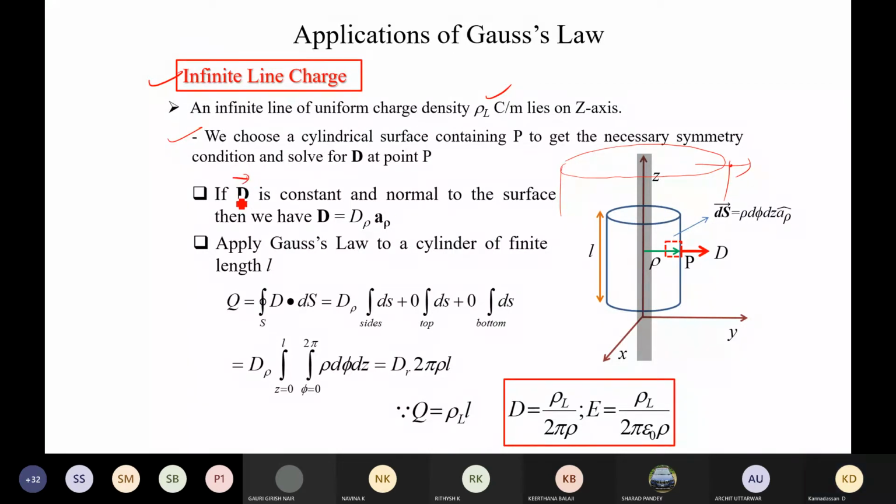So we are going to take this D vector. First, we have to define the D vector. It is not necessary to calculate the D vector, but this is the way we are defining it. According to Gauss law's principle, the D vector, that is the flux lines, will always be perpendicular to the structure we consider. Even if it is a small or big one, we are always going to consider these perpendicular lines alone. In this direction, there is no field component available according to the Gauss law. So this is what we are going to see.